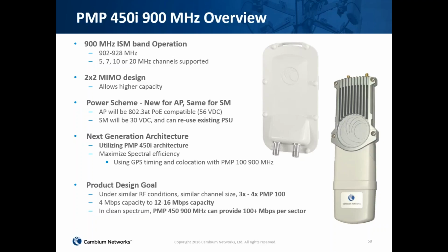If you have those hard to reach customers that are in very rural areas that are surrounded by trees and that sort of thing that you typically can't get access to, even utilizing unlicensed radios, the 900 megahertz system will burn right through trees. So tree coverage and obstacles like that, which have been real tough to deal with in wireless, are now no longer an obstacle with the 900 megahertz system.